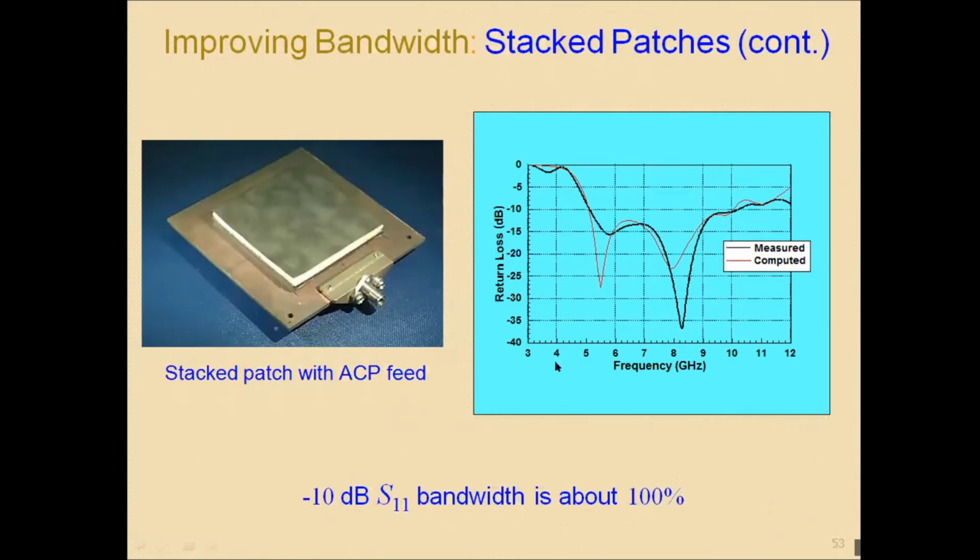See, this curve is very important for antenna testing, right? First, for example, the frequency is selected, the length and width are calculated, and the proper dielectric material and the height of the substrate are selected. After calculating, we fabricate it and connect the connector.